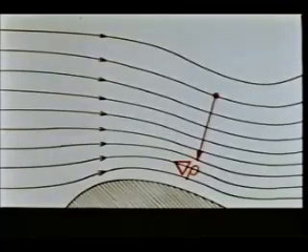The density varies from point to point in the fluid, but because the motion is steady, the density is constant along a given streamline. The density gradient is everywhere normal to the streamlines. Despite the motion, the pressure field is practically undisturbed, so that the constant pressure surfaces are nearly horizontal.